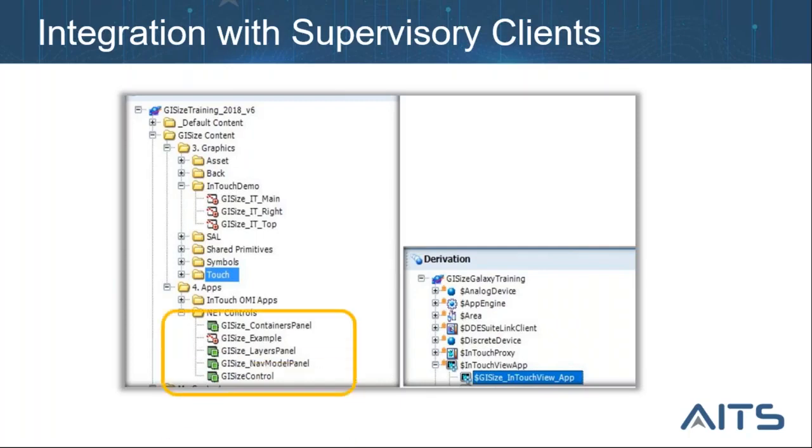the dedicated objects that contain all the .NET controls and embed them in a symbol, because the .NET client control can be embedded in a symbol. You need to do some configuration on that .NET client control using the symbol editor, and then you are ready to go. You can just right away integrate that symbol in a window, and then you can jump to runtime right away.